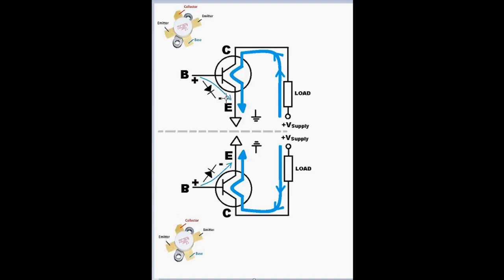And we're going to see, depending on our input signal, these transistors are going to take turns alternating, each one at a time, alternating their paths to ground. So sometimes the current is going to flow through the upper transistor to ground, and other times the current is going to flow from the lower transistor to ground. But in both cases, it's going from the higher potential to the lower potential through the load, two different loads here, as we see, and a common supply point.